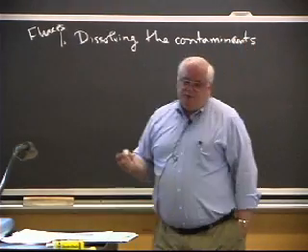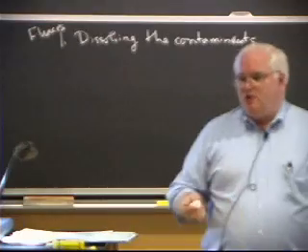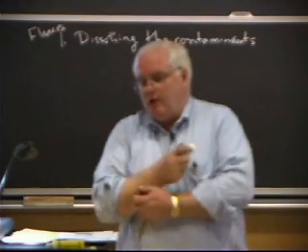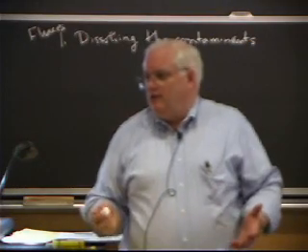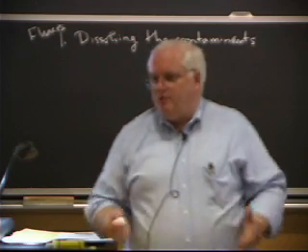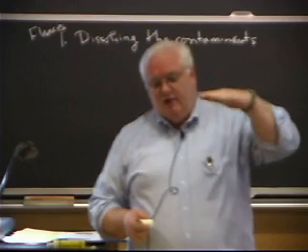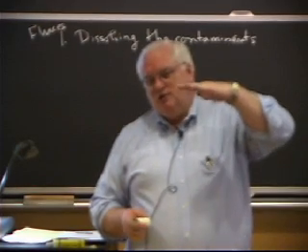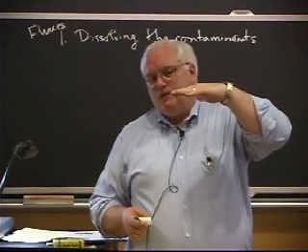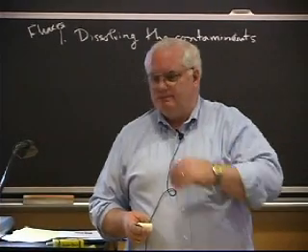Sometimes people, if you're soldering to gold or sometimes even copper, you can just use oil. And the contaminant there that you're dissolving is basically the greases. You've got a hydrocarbon, it dissolves the, if you actually look at the hierarchy of contamination on a surface, it's typically moisture, oils, oxides, and then you finally get down to the metal.